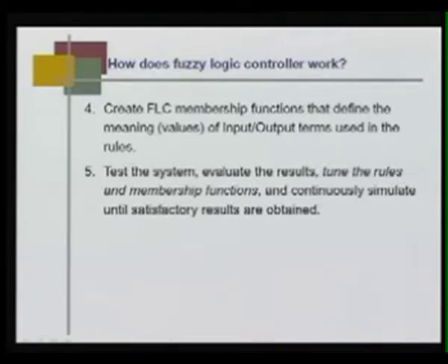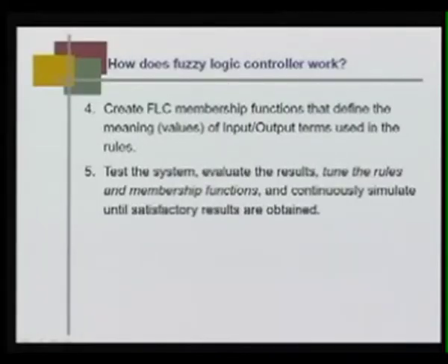Create fuzzy logic controller membership functions that define the meaning, the linguistic values, of input and output terms used in the rules, because a fuzzy logic controller receives the crisp input, but the computation is through linguistic variables, and after that the output is again crisp, because the system out there is processing crisp input and crisp output.